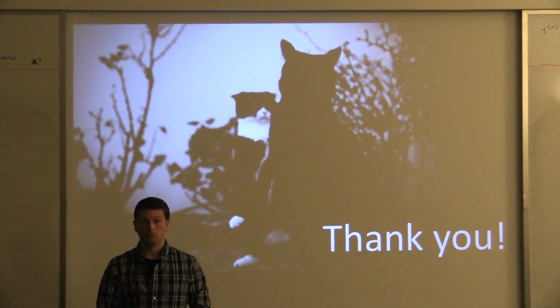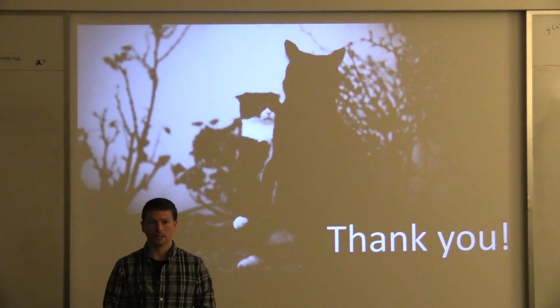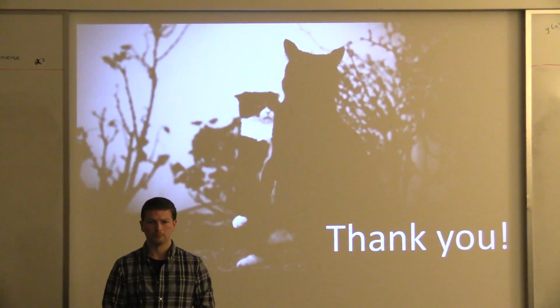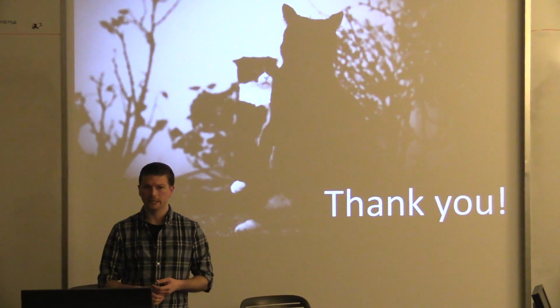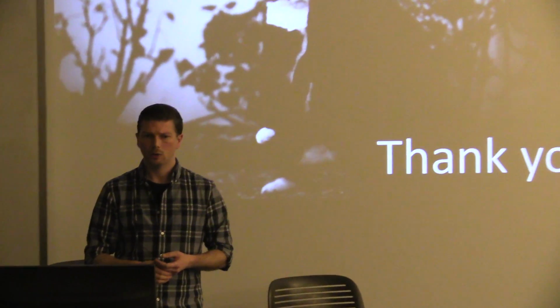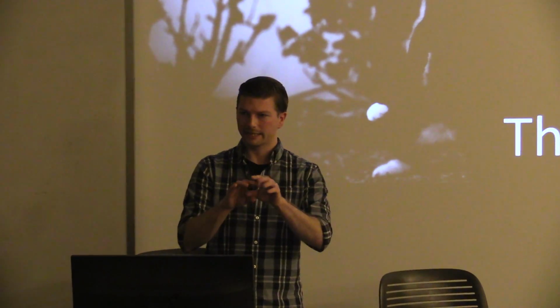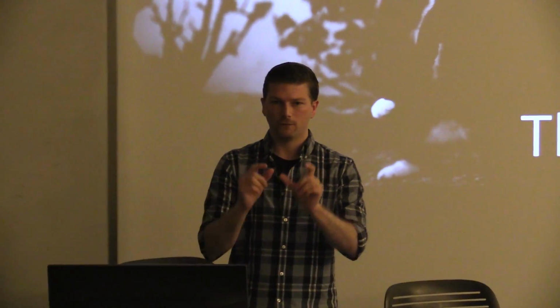There were a couple of papers out of TU Leuven, I think Marc Moonen's group. He looked into this problem and said, well, rather than letting them take any value they like, let's force them to be equal to the early taps in channel 1. So that makes it a bit more constrained. But what comes out of it is perceptually nicer, at least from what I've heard, because at least it's a real impulse response. It's not just a whole random set of taps within that relaxation window.